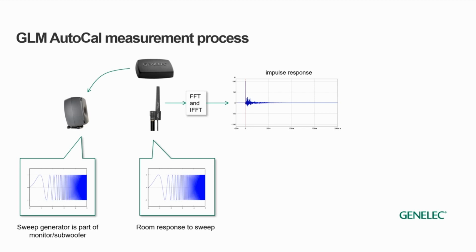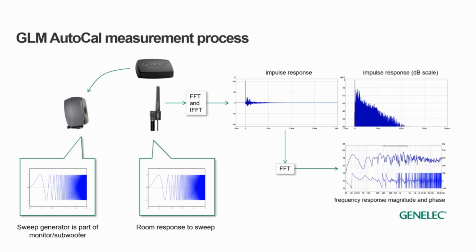This is a backward transformation where we come from the frequency domain to time domain. This inverse transform is actually able to find us the signal that behaves in a way that creates that level variation that we saw. It turns out that this inverse transform creates us the impulse response.